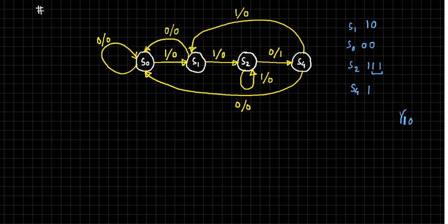This is a binary state machine. What if, instead of detecting 1, we detected 0? We wanted 1 1 0, but we have detected 0, so it should retain the same state just because it's not the start of any valid sequence. It retains state 0 when the input is 0. We should not give any output because we wanted 1 1 0 to be the detected sequence. So both the cases are covered, when the input is 1 and when the input is 0. Come to state 1.